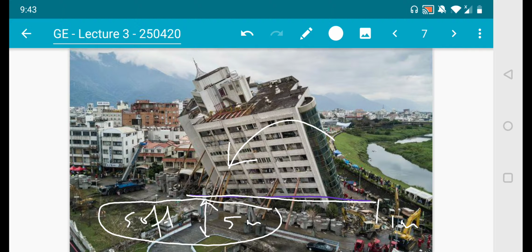What could be the cause of this soft soil is maybe the movement of water. So there is water in here, and maybe this area is prone to rain. Maybe this accident happened after a heavy rain the previous day or something like that. Everything looks wet, and that's basically how you interpret. After this interpretation of the photo, you're likely to go to site to make more detailed observations. This is what you're going to do as a geotechnical engineer. It's pretty fun.